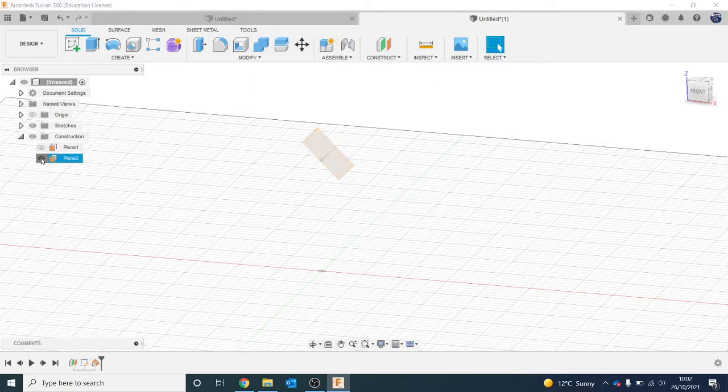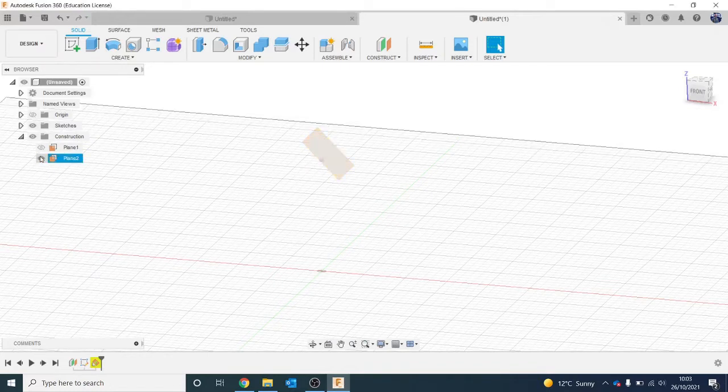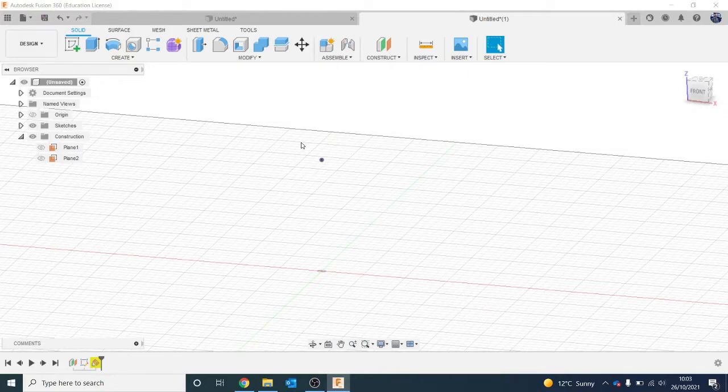Next, what we'll have a look at, I'm just going to get rid of that because I don't need it. So that warning, by the way, that just popped up on my screen in yellow here, is saying that I've removed that line, so the reference for that plane no longer exists. It's not a big deal because I'm just showing you what these planes do. But if you're going to have a big model, you don't want to just delete the lines like that.